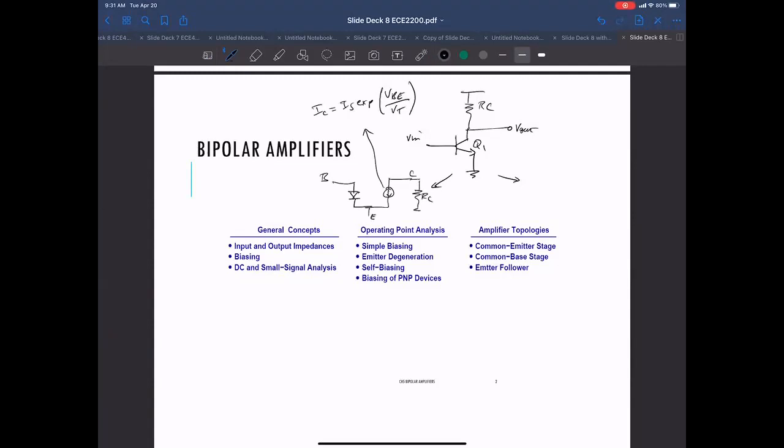The small signal model here is, we had R_pi, and we had a current source, that's the g_m V_pi. And we'd have the R_C and the emitter here, base. So we basically looked at this as an amplifier circuit.